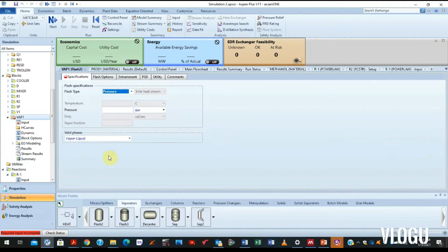With a valid phase of vapor and liquid, because some will be vaporized while there will still be some liquid, given the differences in boiling temperatures, right? Now we can use pressure to suppress the evaporation of unwanted products. I tend to slightly increase the pressure during the flash vaporization process, just to suppress possible vaporization of other components that are not methanol, right?